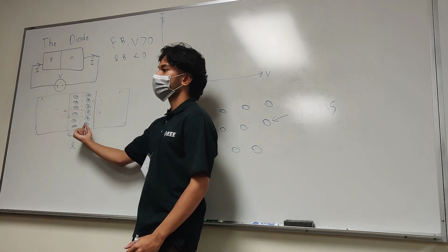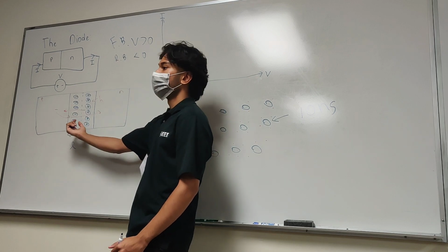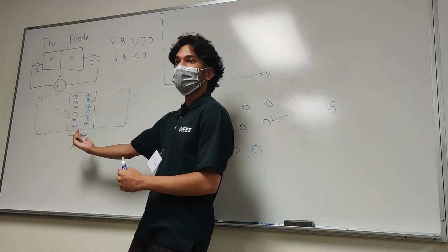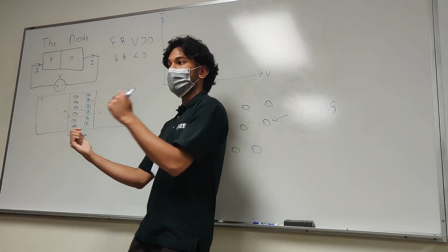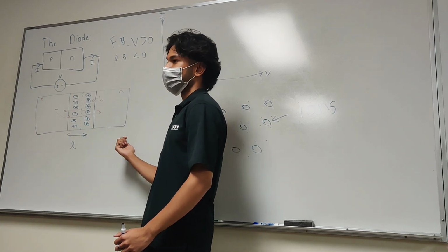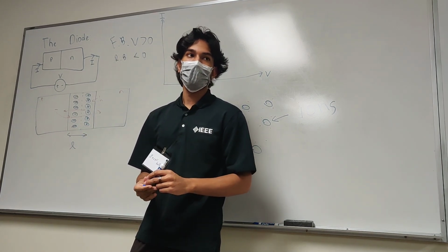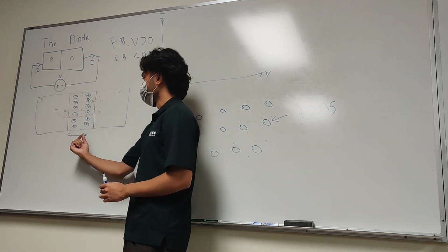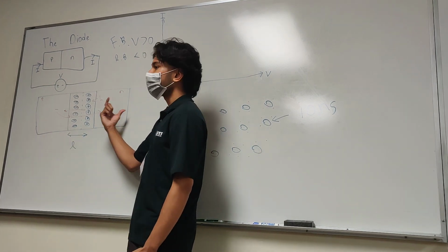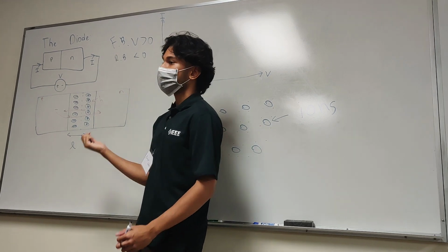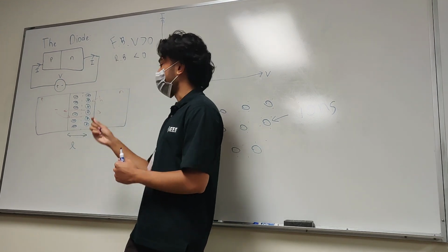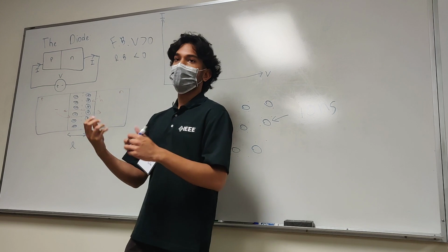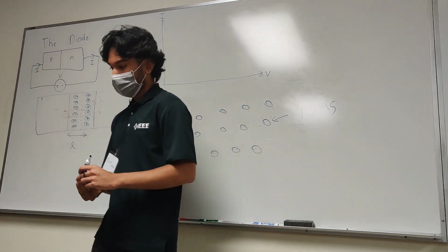The electric field gets stronger. We have a stronger flow now. Because our electric field is stronger, our carriers can get pushed even harder, our current is going to increase. General first order idea behind it. That kind of makes sense? Similarly, in reverse bias, this will extend, and we have less electric field, which means carriers are not being pushed as hard from this side to that side, current goes down, okay?